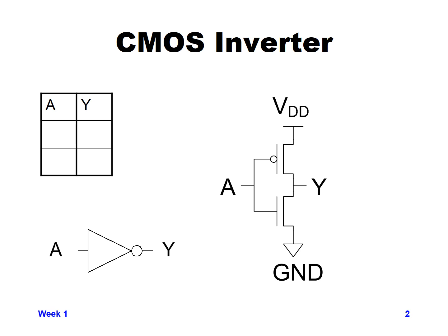So on the right hand side, that shows the circuit level diagram or transistor level diagram of this circuit. If you look in the lower left corner, you'll see the symbol level diagram of this circuit, where that triangle with the circle on the right hand side is representative of the transistor level diagram on the right side, but it's an easier way of depicting it. And so a lot of times you'll see these symbols that stand for a certain amount of logic that will be used to make the circuits a little bit more understandable. And we'll get into more of these symbols later.